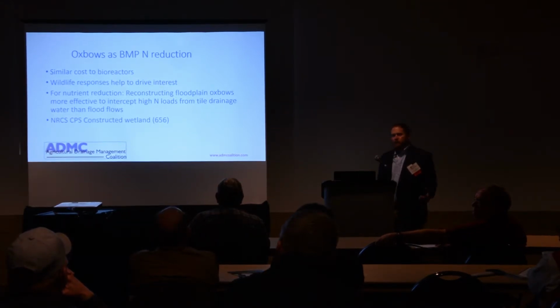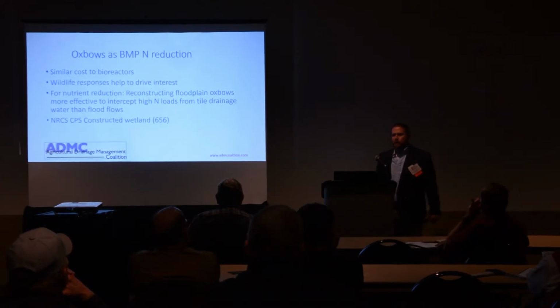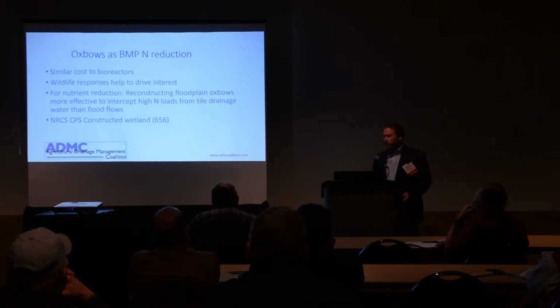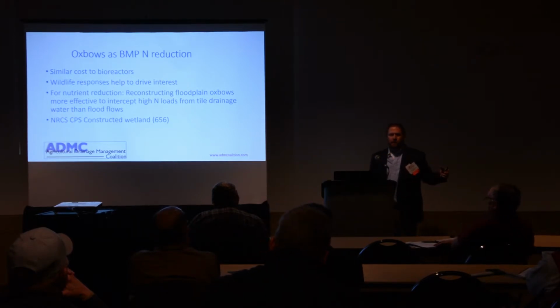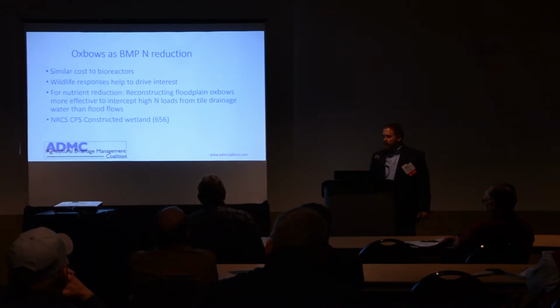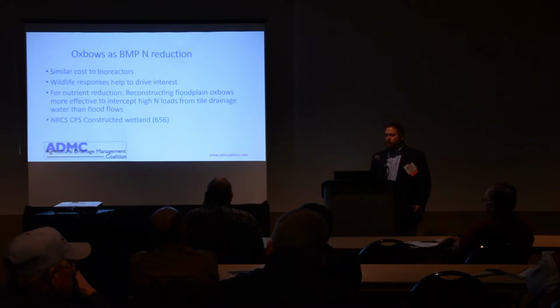Yeah, and anytime you can manage that water somewhere, hold it back, get some retention time there, we're going to see some of those biological processes take place and start removing it. It's a little tricky to monitor for it, just looking at it, take a sample from the tile pipe and then the outlet, because there might be a little dilution that goes on too, because some kinds of groundwater have lower nitrate concentration. But yeah, anytime you can try to hold that water back and give it more time before it reaches the stream, generally we'll see some nitrate reduction come from it.